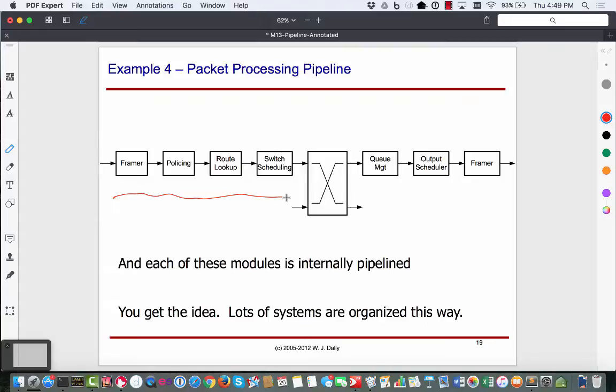Whereas if you had the same gates and you were designing them yourself, you can certainly do a lot more than one instruction per clock tick. And that's really what it boils down to: for the same speed, I can get away with fewer gates, or for the same number of gates, I can have a lot more performance. So really high performance applications tend to move away from processors to designing at the level of hardware and hardware-level parallelism.